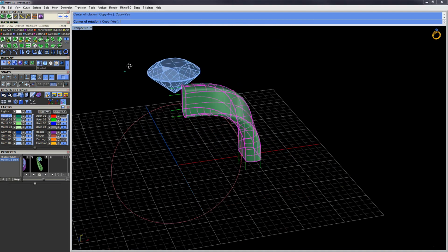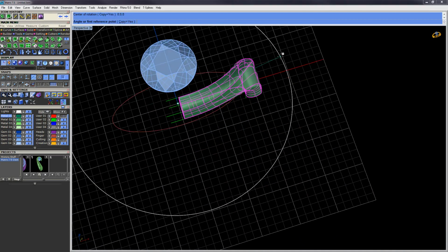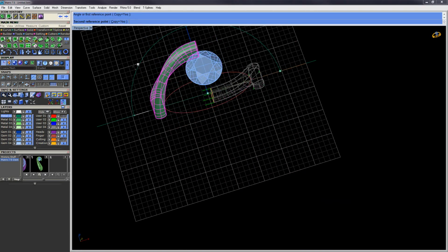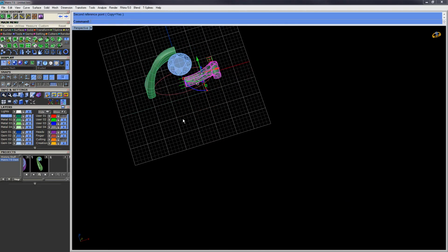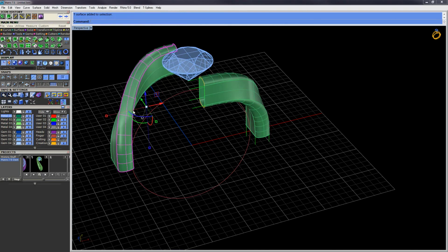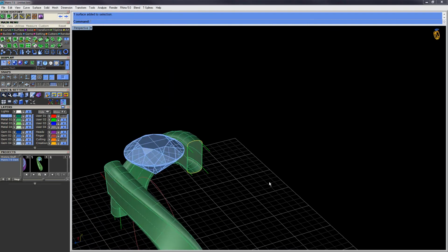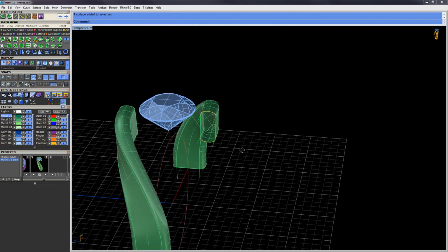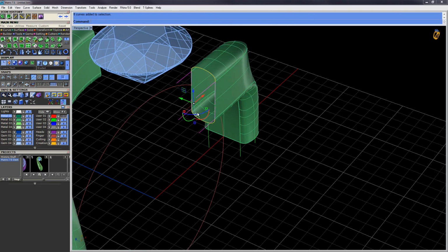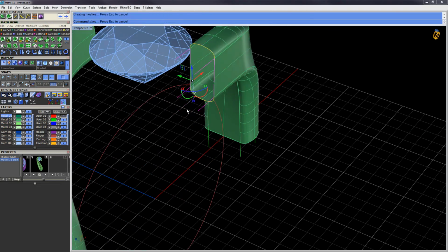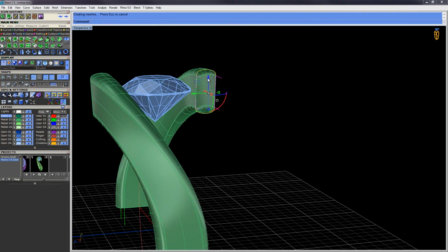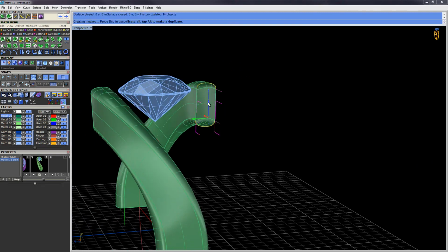We'll choose copy, and we will rotate this with a copy to one side from the next. So these swept surfaces here are a child of all of our swept surfaces there, because rotate with copy is history enabled. So if I were to grab this set of blend handles there, you can see as I move that up and down, my rotated copy is moving about.